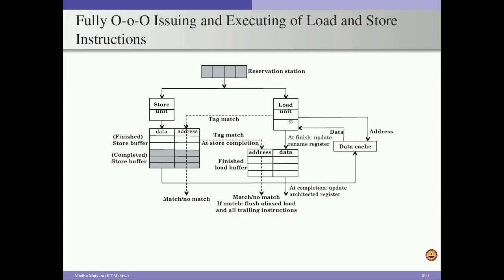Now, once we have the data at the end of the third stage of the load instruction processing, we write this value to the rename register to update the rename register content. With that we finish the execution of this load instruction.